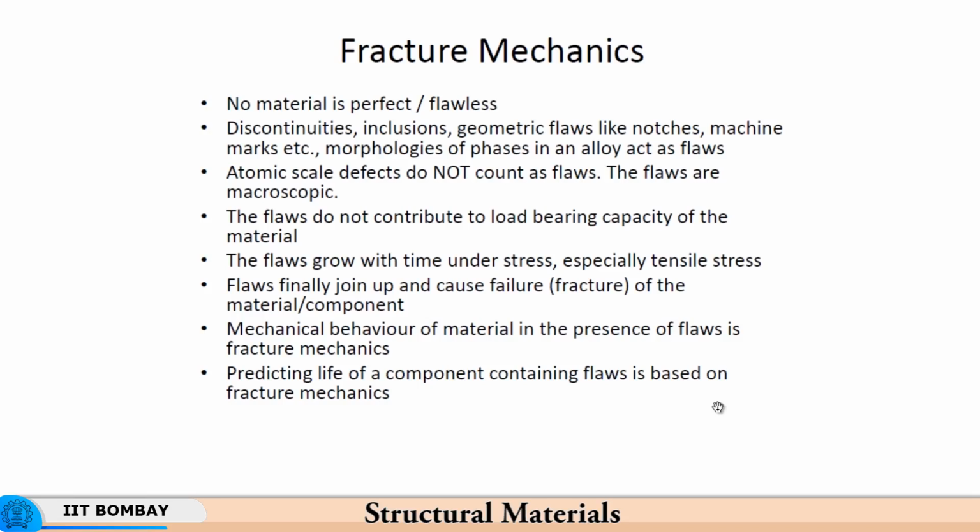Flaws join up to cause failure. So, I talked to you about void coalescence. So, you have these again voids which essentially are flaws of a macroscopic nature, and these flaws will join together to create a crack. So, sometimes once the crack is generated, it can propagate precipitously leading to a sudden fracture. Mechanical behavior of materials in the presence of flaws is fracture mechanics.